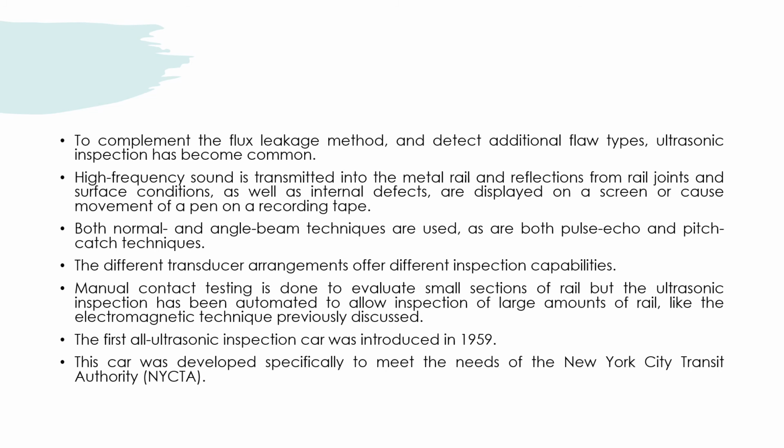High frequency sound is transmitted into the metal rail. Reflections from rail joints and surface condition, as well as internal defects, are displayed on a screen or cause movement of a pen on a recording tape.